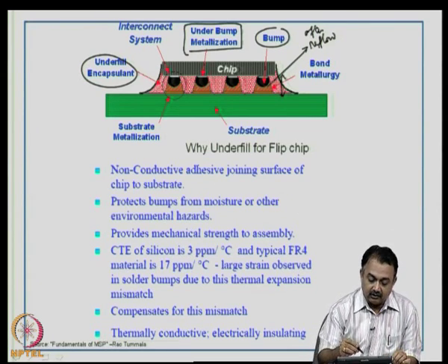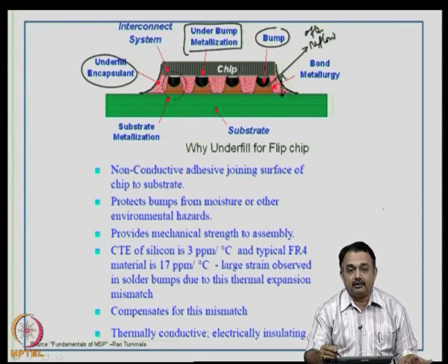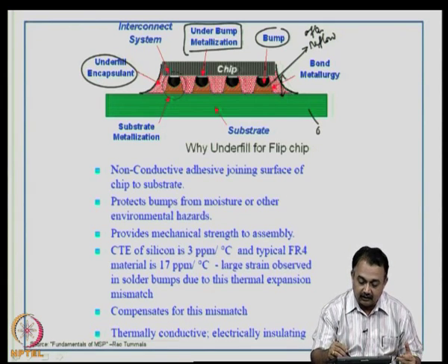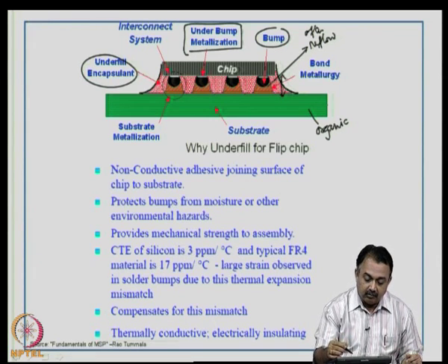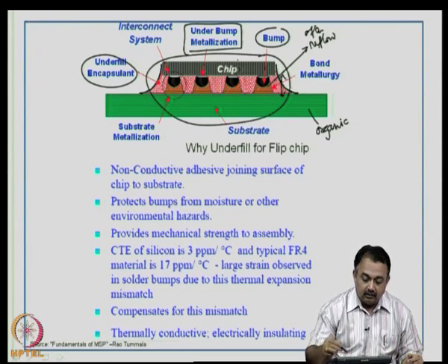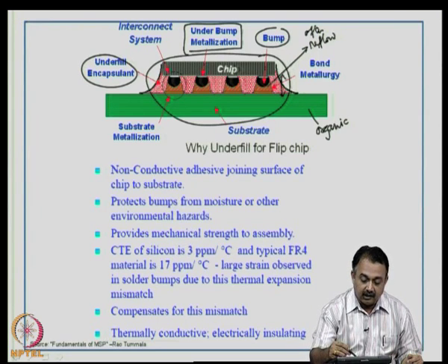Now, underfill is required because in the previous slide we talked about thermal mismatch, right. If you do not use an underfill, there is going to be a thermal mismatch between the chip and the organic substrate, if this is an organic material like an epoxy. The thermal coefficient of expansion of the silicon die and the organic substrates are different, and therefore, if you imagine a power up of this system, due to heat building up at the die surface, you can expect the die to crack. There can be solder joint fatigue as well as warpage on the substrate.